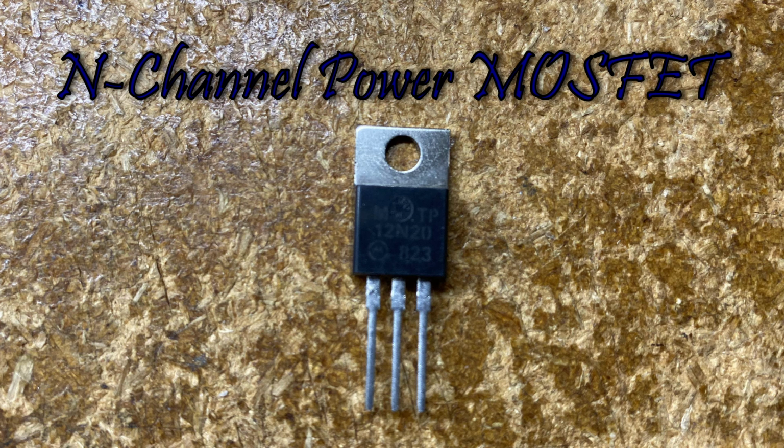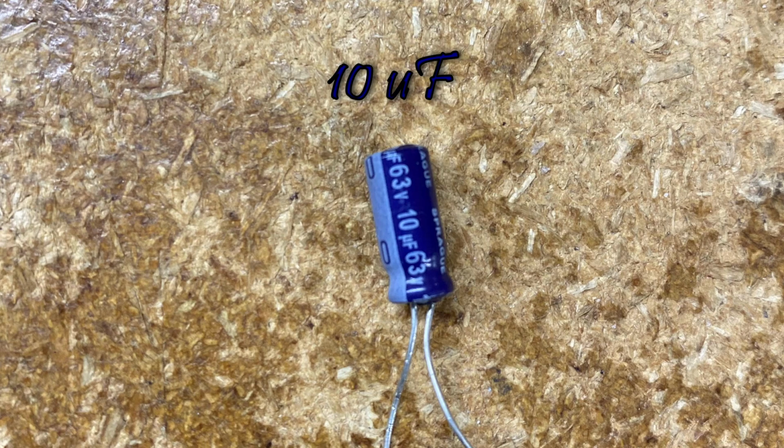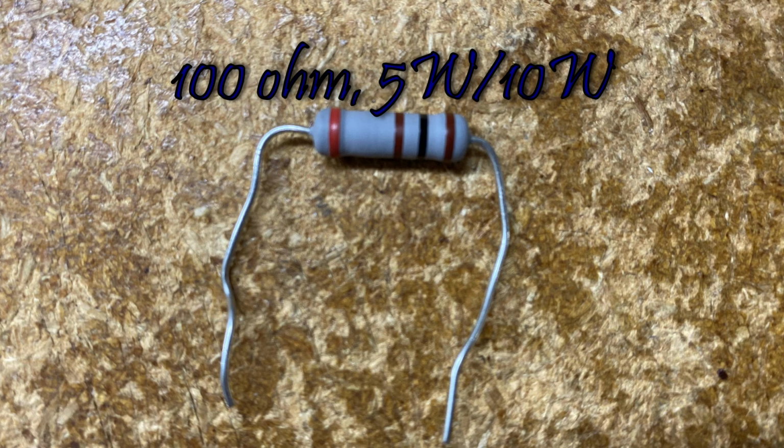In this video, I've used an inductance of 500 microhenry, capacitance of 10 microfarad, one N4007 diode, and a 100 ohm resistance 5 watt or 10 watt rating. If you connect a regular 0.25 watt 100 ohm resistor, beware, it can burn up emitting smoke.